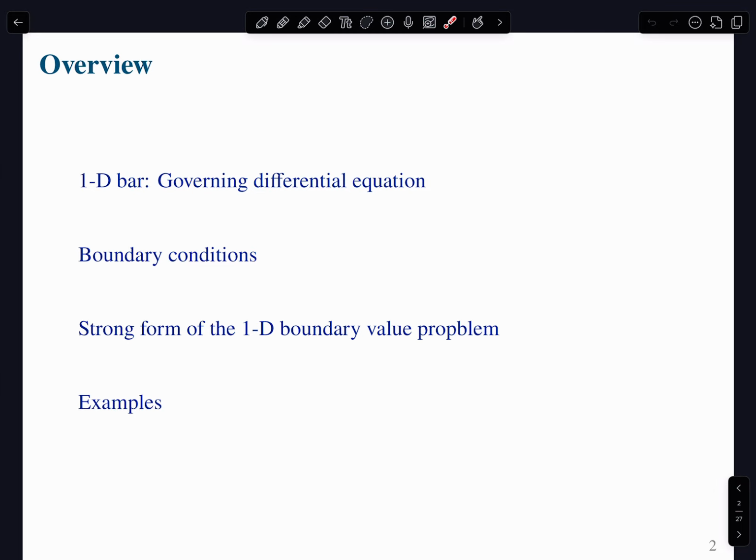These examples are, of course, not yet finite element solutions, but we are going to eventually get there, right? Hopefully, with the examples that we see here, we're going to get the strong form solution, right? So the analytical solution for those very simple problems. And ideally, when we discretize our system with the finite element method, you will be able to understand how good your approximation is, because we have an analytical solution, right? So if you have an analytical solution, this is great. You can always obtain your exact strain energy given an analytical solution.